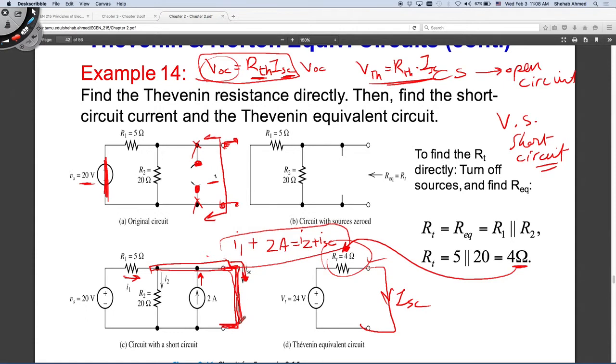This short circuit is placed across anything in parallel with it, right? So it's placed across this current source, and it's placed across this resistance. Is it going to affect the current in the current source? No, the current source will always produce this same current, right? But if I place this short circuit across the resistance, will any current flow in the resistance? You have this short circuit here, right? Current coming in here, we'll see what?